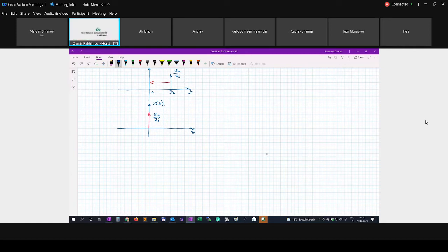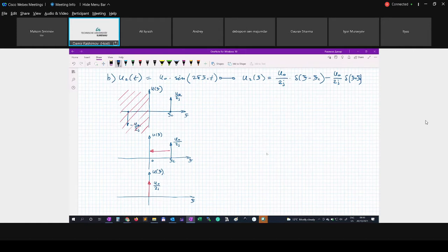We started with a signal which included two delta pulses, yeah? And if you calculate the energy of the original signal U, how do we calculate energy? You take the squared value of the magnitude of the original signal and calculate the sum of all frequency components. Yeah, let's try to do this. We have absolute value squared.